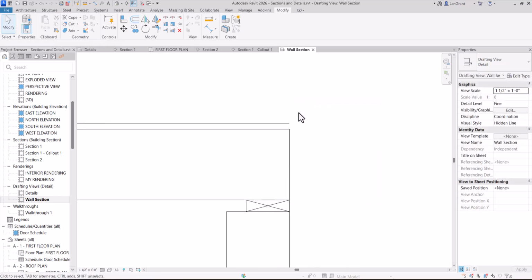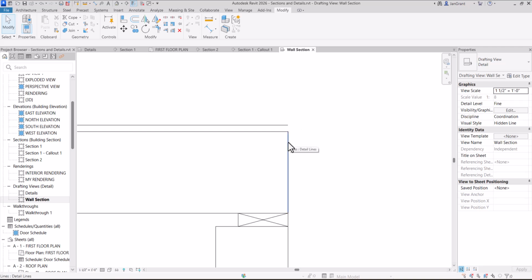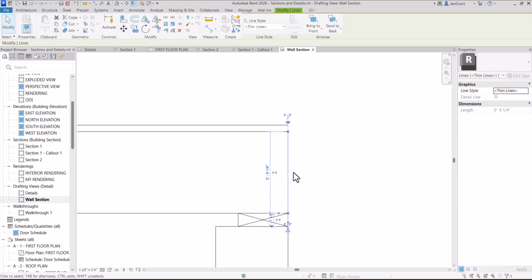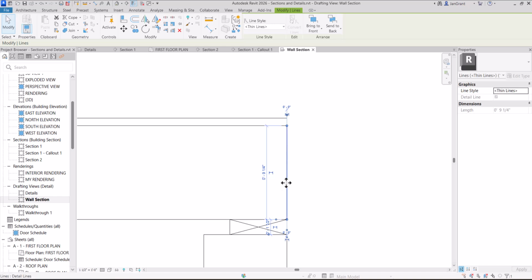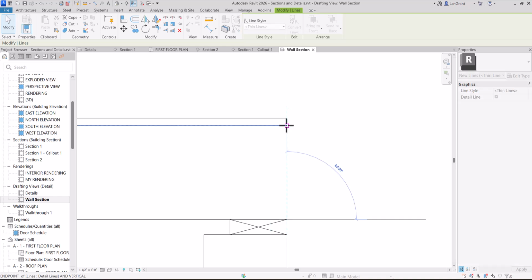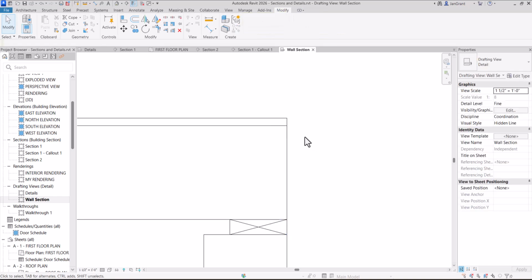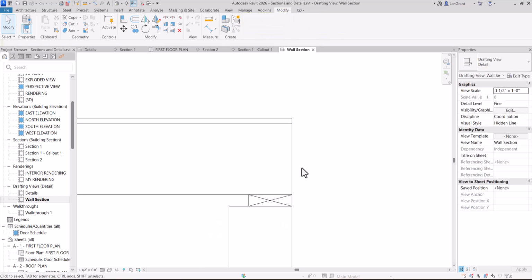Okay. Now we can stretch lines too. So I can click on the line that we drew over here that's 9 1/4, and hold your left mouse button down on that little circular grip at the end of it and pull it up to the other one, and now you've got it stretched out. All right, so I think we're ready to bring in our 2x10 and our 2x4.